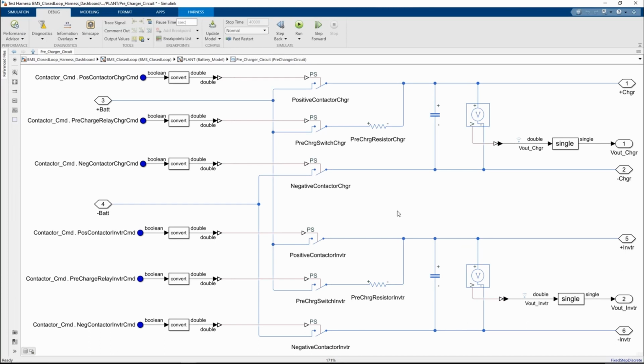Before connecting a battery pack to a charger, it is important to pre-connect them via a resistor to prevent an excessively high current from rushing into the pack and potentially damaging it. This pre-connection needs a special sequence that we will see when we describe the BMS algorithm.